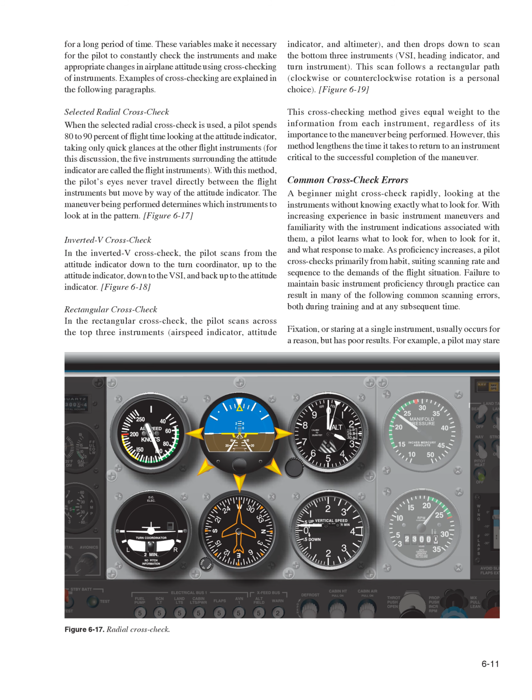completion of the maneuver. Common crosscheck errors: a beginner might crosscheck rapidly, looking at the instruments without knowing exactly what to look for. With increasing experience in basic instrument maneuvers and familiarity with the instrument indications associated with them, a pilot learns what to look for, when to look for it, and what response to make. As proficiency increases, a pilot crosschecks primarily from habit, suiting scanning rate and sequence to the demands of the flight situation.